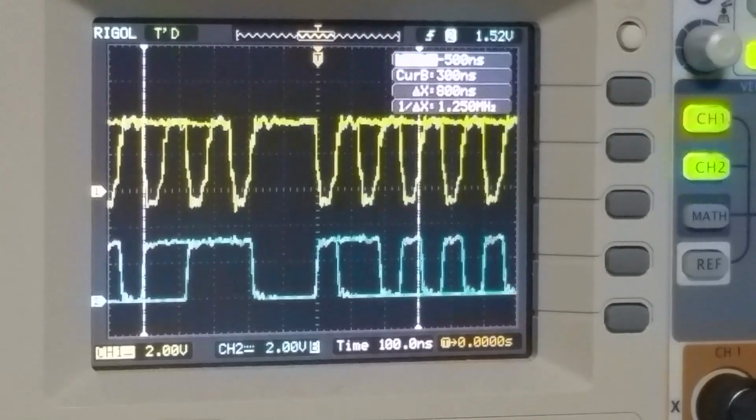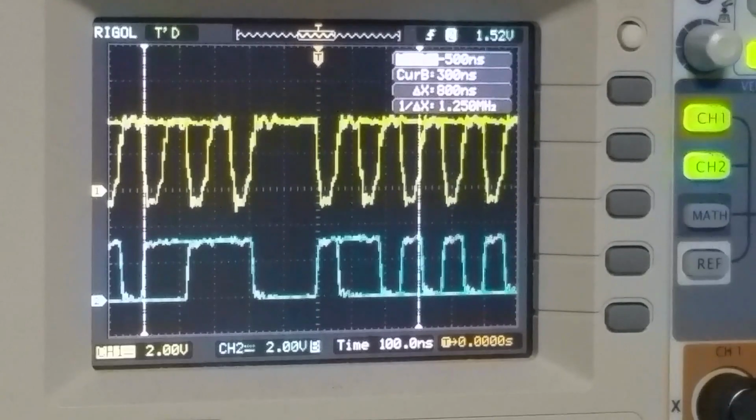So if you try to spread one read access from, for example, a slow ROM across 2 cycles, there will be a phase where the clock is low, and in the first half of the second cycle, the CPU will still send out the bank address and will push it against the data that is coming out of the ROM in this period of time.